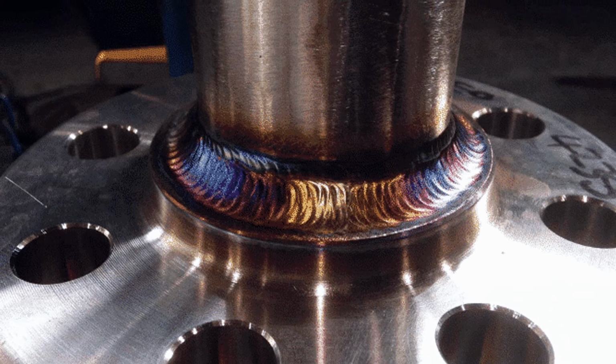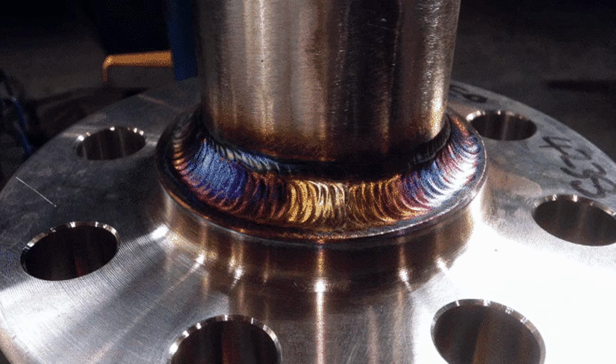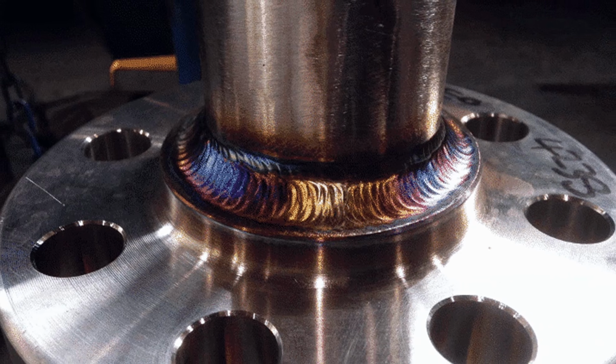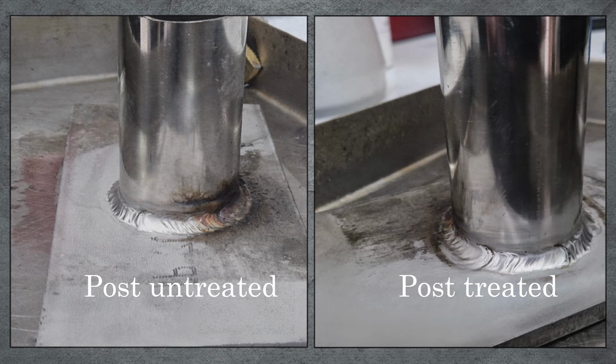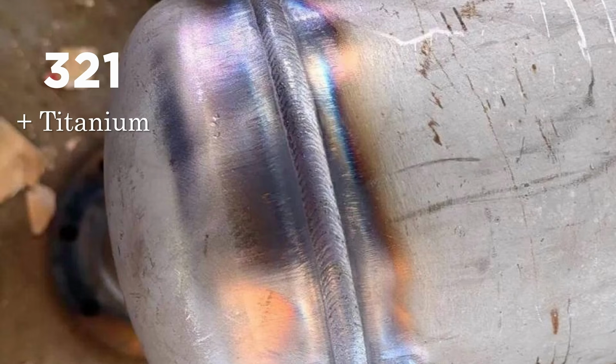So even chromium-rich stainless steels like 304 or 316, if left untreated, unpolished, or not annealed after welding or heating, even if the surface looks clean, the grain boundaries near the weld may already be chromium depleted, and the chances of intergranular attack are high. So in such conditions, where we are not doing any post-treatment or annealing after welding, it's better to use stainless steel grade 321 because it has titanium added to it.